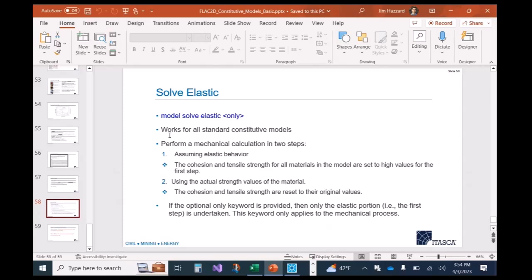When it makes everything elastic, you can have humongous stress changes and boundary condition changes, with gravity or whatever you want, and all those waves are going to bounce around in there. It doesn't matter because it's elastic, nothing fails. It's going to come to equilibrium, work out what the stresses are, change everything to be plastic or potentially plastic, and then things might fail depending on what the stresses are, but not due to these gigantic force changes, just due to the static stress. Does that make sense?